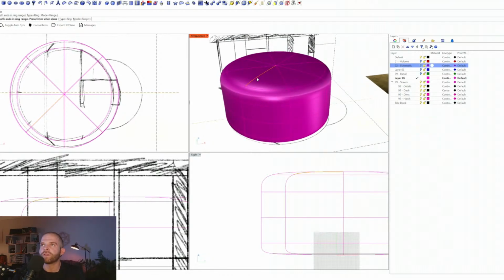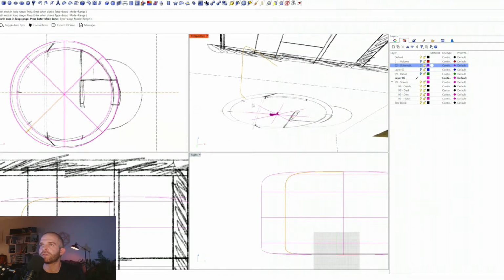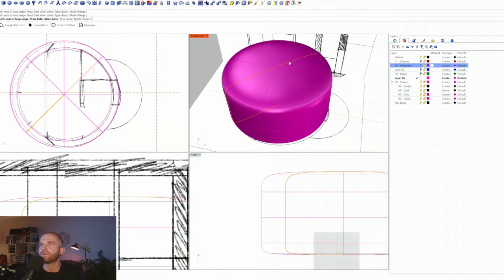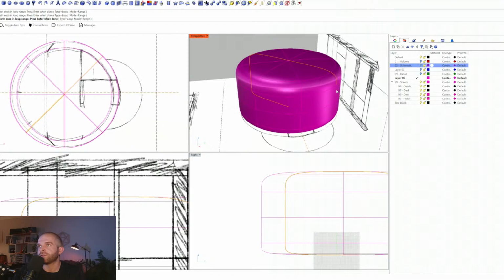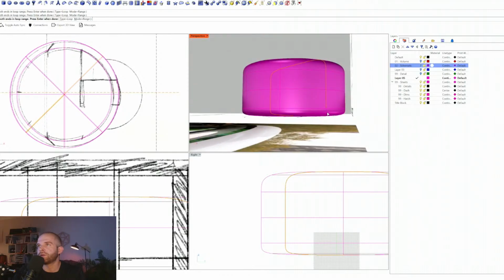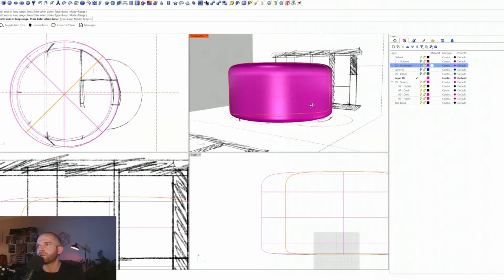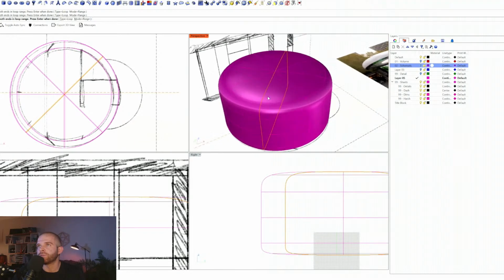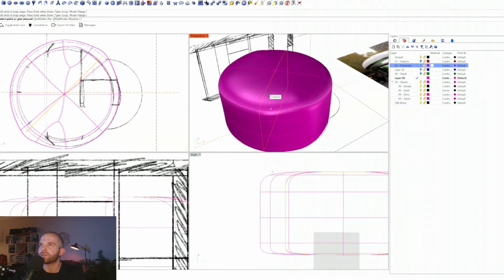No, in order to do a ring, it has to select something that goes all the way around. So we'll go back to loop, and we'll select this whole edge and its opposite edge. Let's see if by having it mirror on both sides and actually completing the loop doesn't destroy our topology like that. So no, now we're just getting it on both sides.